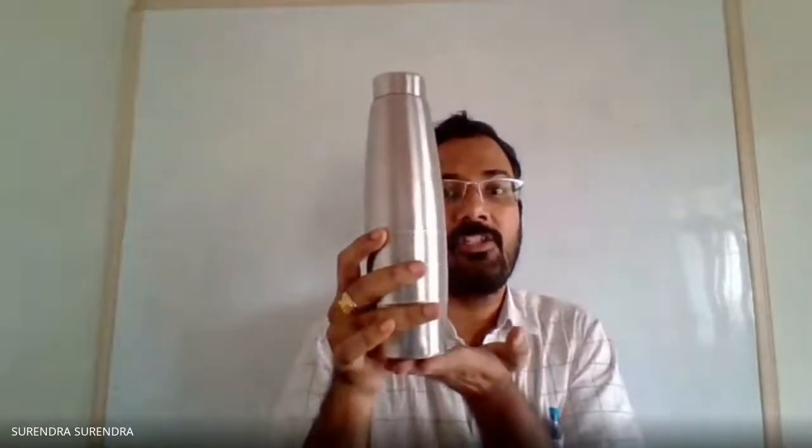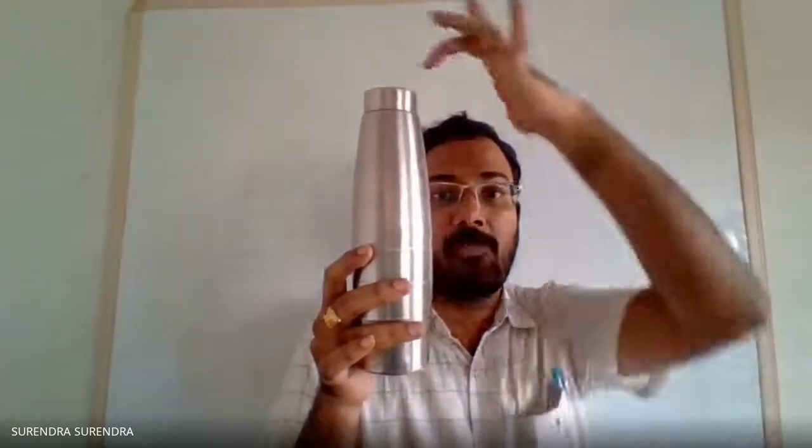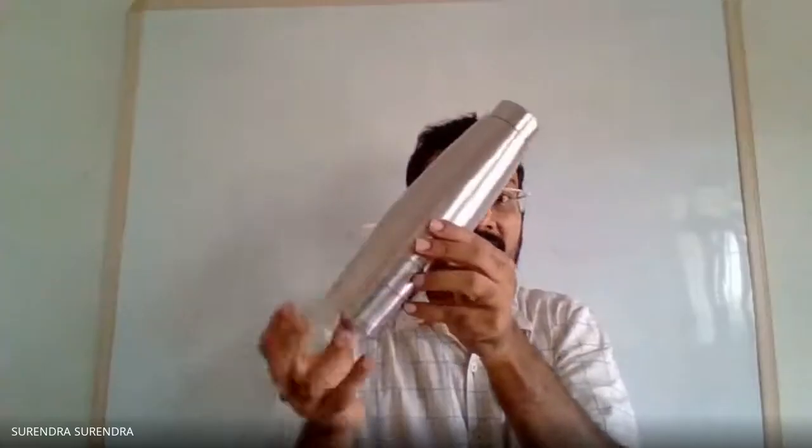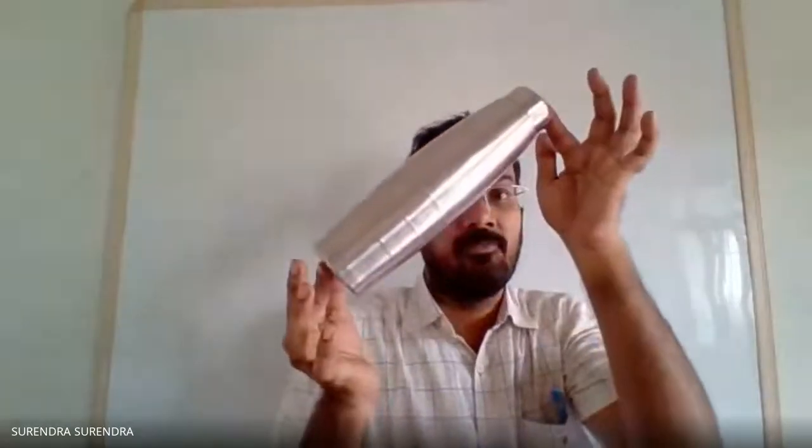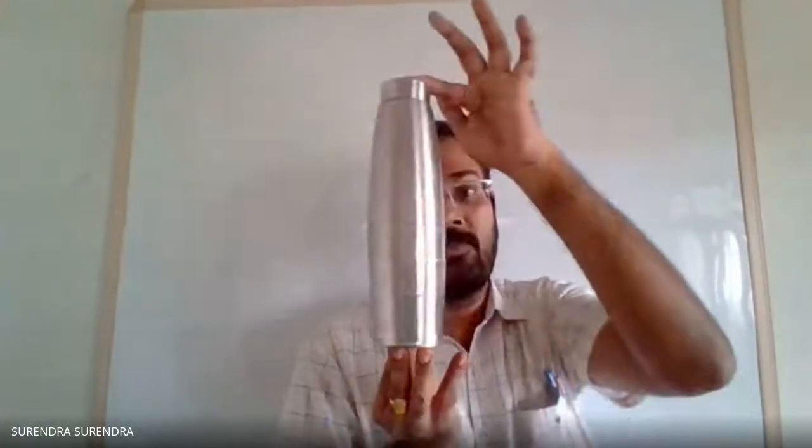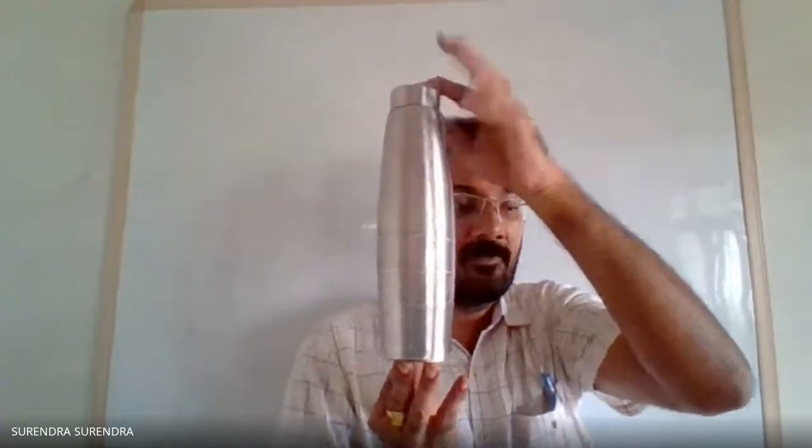So we'll assume the initial position with the axis perpendicular to HP. So a cylinder. When the axis is perpendicular to HP, this is the position. We can see the true shape of the base in top view. Actual second condition is given as the axis inclined to horizontal plane. So we're assuming axis perpendicular to HP. So we'll draw the true shape in top view.